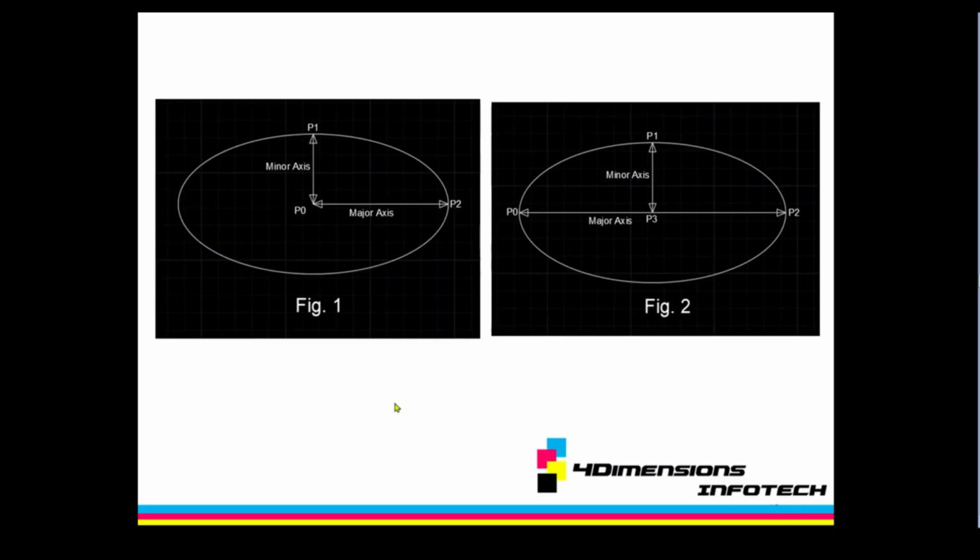Now we are learning the ellipse command. In ellipse we have two types, that is center method and then minor and major axis method. In figure 1, first we have to click the center point and then you have to click the half of the x distance or half of the y distance, that is minor axis and major axis. In second pick we have to click the first point and then give the major axis, and then from the center point you have to give the minor axis.